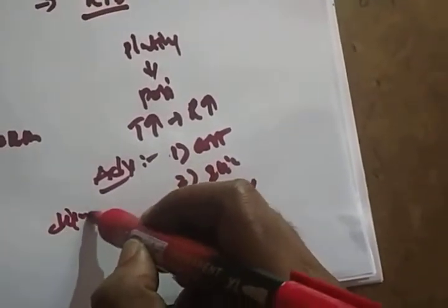And what are the disadvantages of a resistive transducer? The sliding wire requires more power, right? And noise will be generated across the slide when moving the sliding wire across the resistance. What are the applications? Temperature detector, strain detector, pressure detector, displacement detector, resistivity detector, right? All these things we discussed.